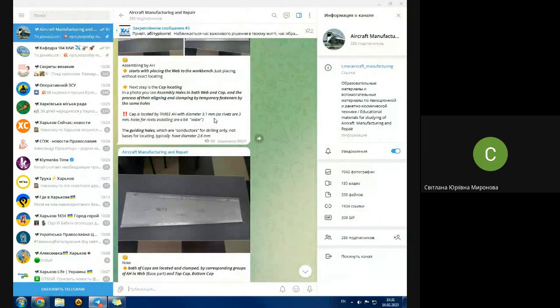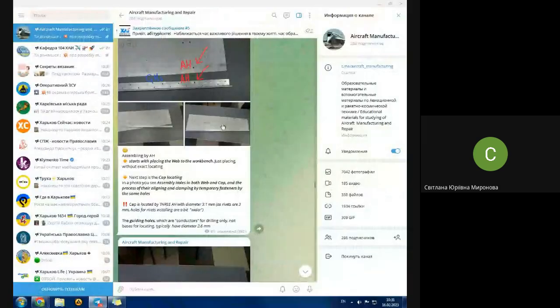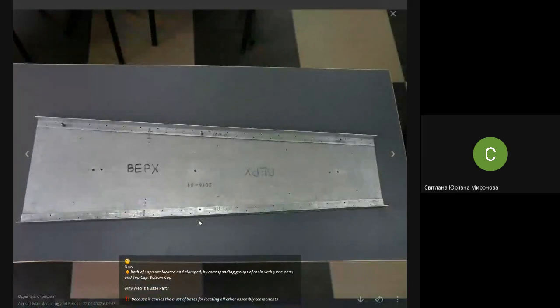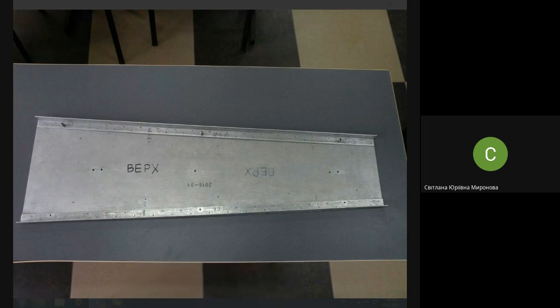Once again, after you have aligned everything, it's not fixed yet, it's not clamped. As soon as you touch it, it's already misaligned, and you must clamp it. How may you clamp it? In our laboratory class, we have so-called technological screws and nuts. They are very convenient for installing, but a little bit longer to install. They are simple. They do not demand any special tooling.